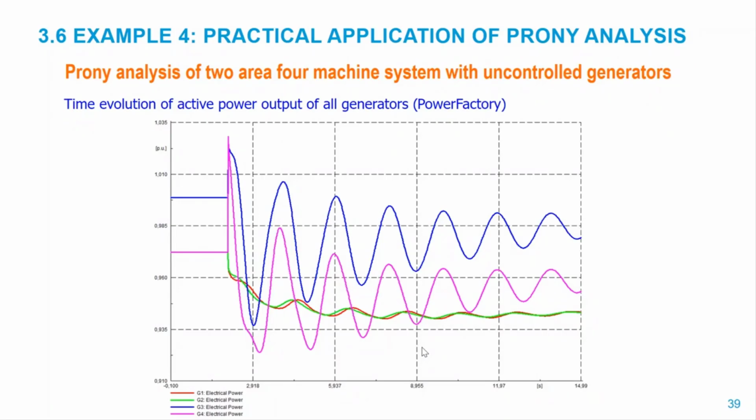In PowerFactory as well, we can run a dynamic simulation, or time domain simulation, by considering an event. We can have, for instance, a scenario of highly loaded condition with export from one area to the other, like in Chapter 12 of the book by Prabha Kundur. Then we can apply a three-phase fault, for instance, at one of the ends of the tie line, and we will see the inter-area mode oscillation excited.